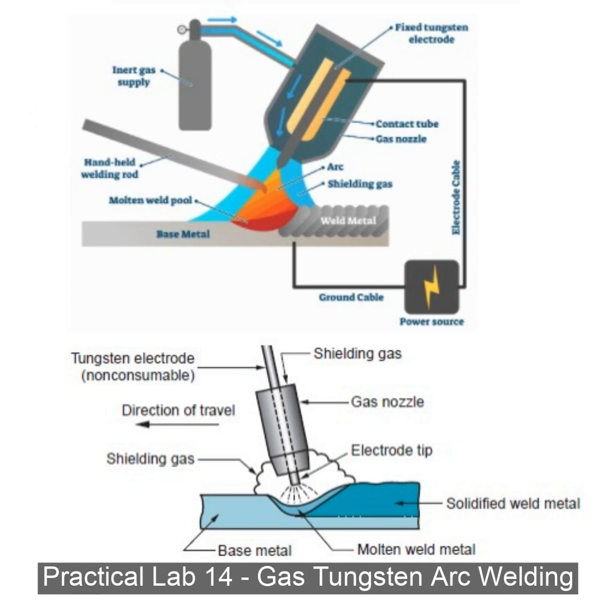Tungsten has a high melting point, and tungsten is not consumed in this operation. In this operation, a constant stable arc gap is maintained at a constant current level. The filler metals are similar to the metals to be welded. One more thing, in this welding process, no flux is used.